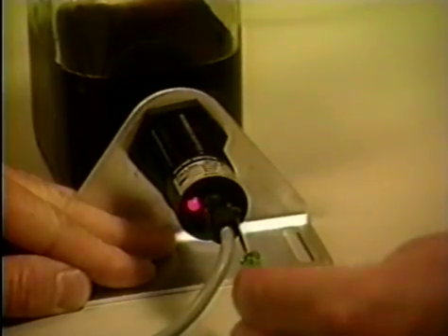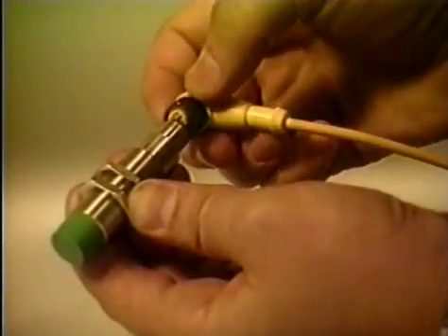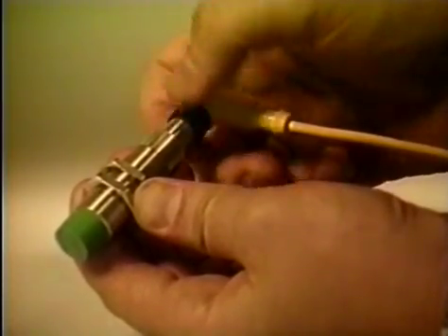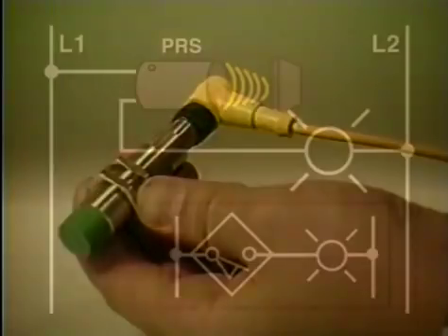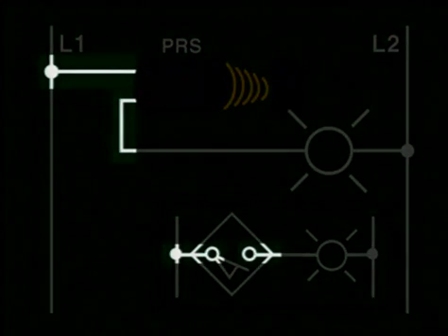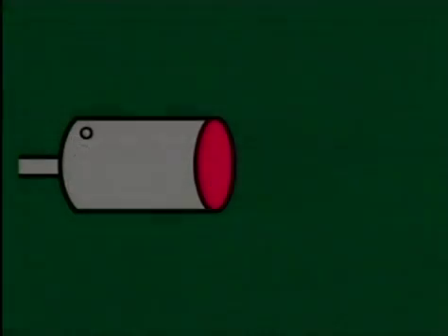Proximity switches must be adjusted to detect a part at a particular distance, and it is advisable that this adjustment be done prior to the actual field wiring. Once the adjustment is done, then the field connections can take place. If there is a problem with the switch detection, it may not necessarily be the contacts or the sensor itself.